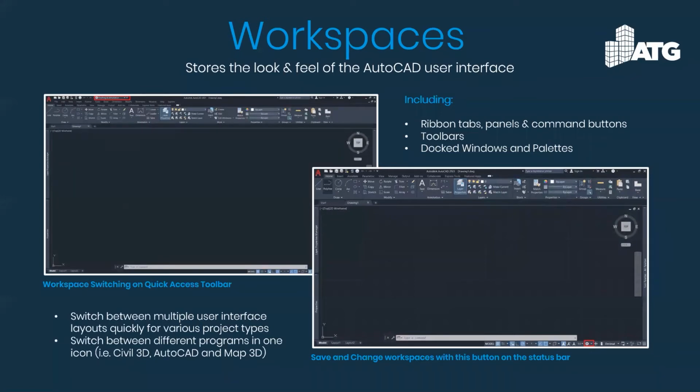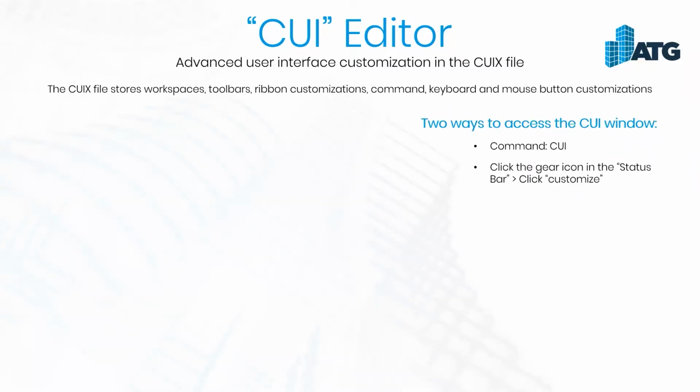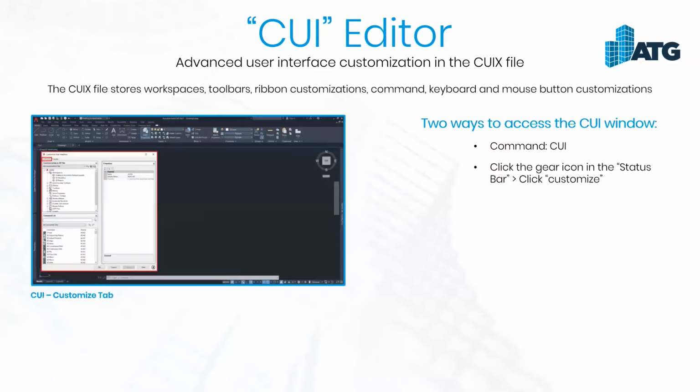Oh, I guess I could show you how to put the AutoCAD interface into architecture now. It's kind of a good segue into that because we're going to talk about the CUI editor. This is that advanced user interface customization that I mentioned. We have a whole webinar. Kyle Davis did an excellent webinar about this. The CUIX file I mentioned stores all of these settings, everything on the user interface, all of your buttons and menus.